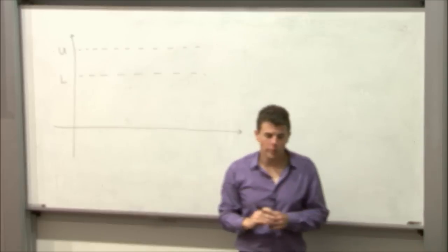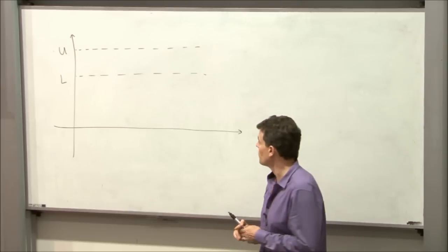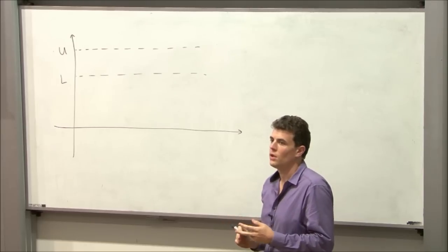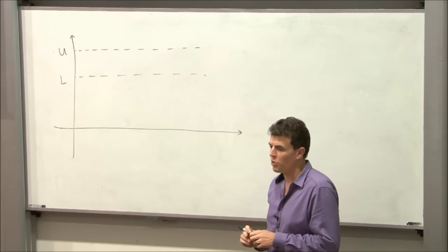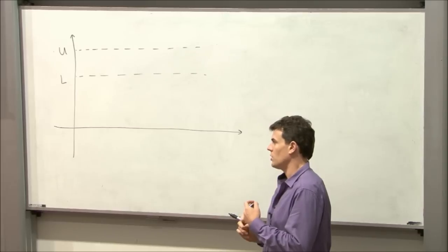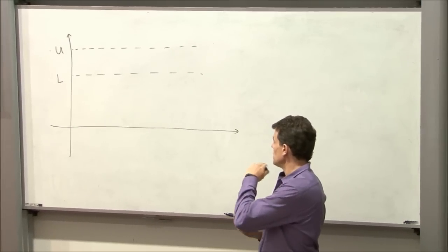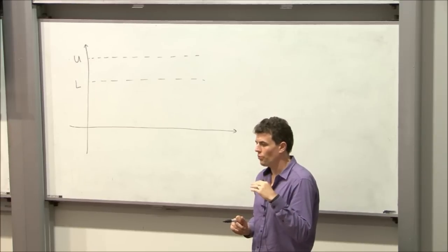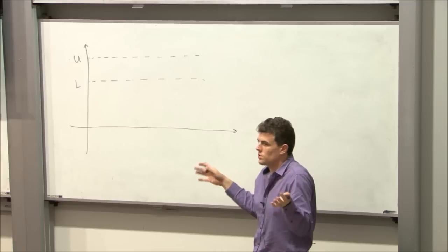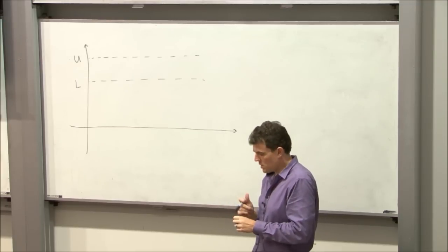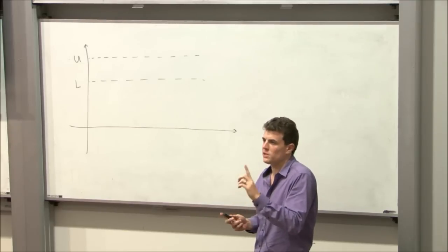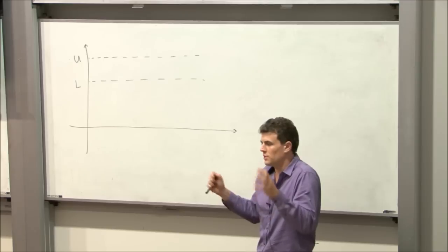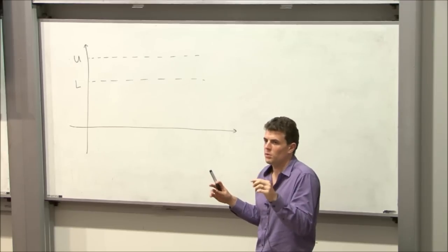So when we talk about the strength of aircraft components, we tend to talk about two different strength levels. There's the limit strength and the ultimate strength. The limit strength is the strength of the component, assuming that it's the highest load that the aircraft would see in service. So the limit load, the external loads that we would put on in our load case, is meant to be something that an aircraft might see once in its lifetime. So the worst combination of load factors and gusts and everything together would be the limit load.